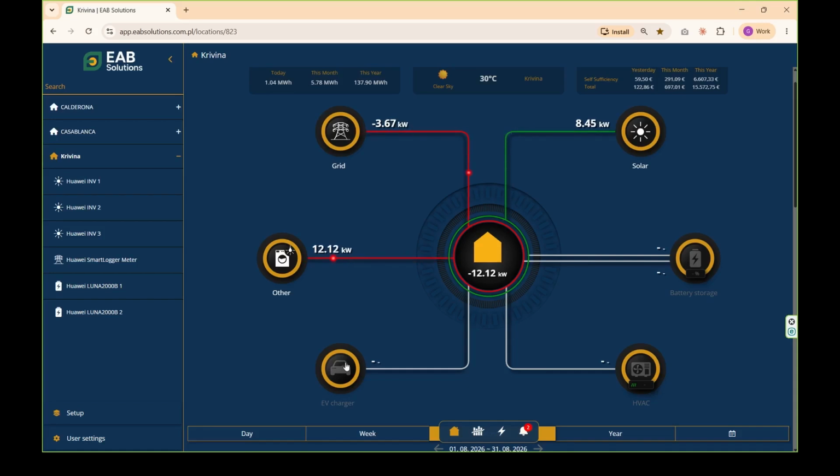And on this platform, all the charging points can be monitored, how they are, prioritizing charging of some points over others, limiting charging according to the electricity price. You can perfectly well set the charging points to charge only when there's PV surplus, or when the electricity tariff is very low and very cheap, so they charge heavily at those times. And if the tariff is very high, the charging points automatically either stop charging or drop their charging power a lot, so as not to create too high a consumption.